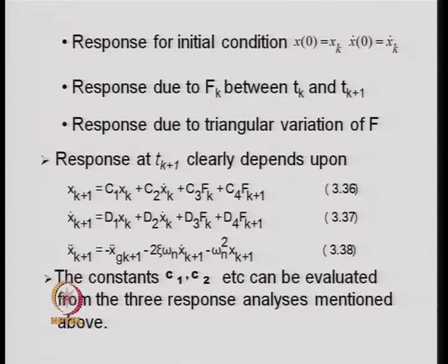That is, the initial condition that exists at the time step k. With that initial condition, the single degree of freedom system vibrates as a damped free oscillator, and because of this vibration there will be some response produced at Tk plus 1, that is the next time step.